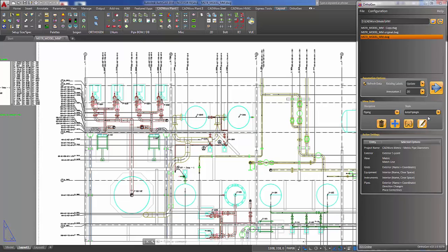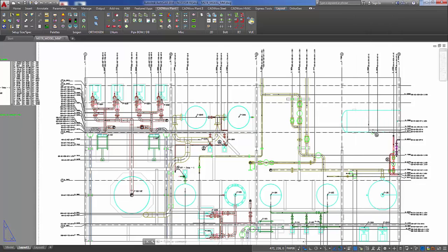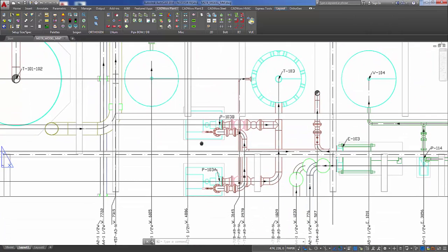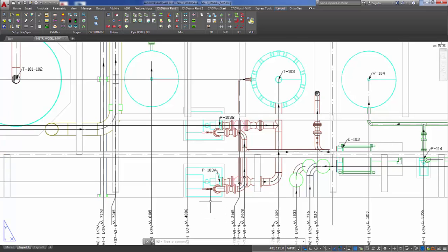Sometimes that's not possible, so we do give you an option, a command, that will allow you to permanently assign view styles to a viewport. The command name is Viewport Style, and once you enter that, you can list the styles assigned to a viewport, add a style to a viewport, or clear all styles.